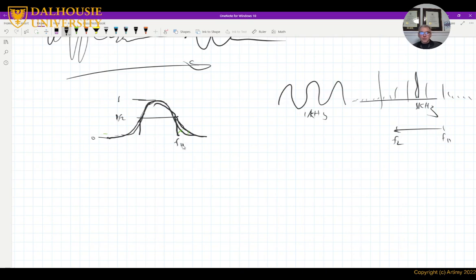This is the highest frequency and this is the lowest frequency, and this is my bandwidth, right? And the rest is below half power, so I'm going to ignore it. As a result, even if there is an overlap between two adjacent channels, the overlap will not be big. The half power point is given as minus 3 dB. You will see when I do 10 log of half, I get minus 3 dB.